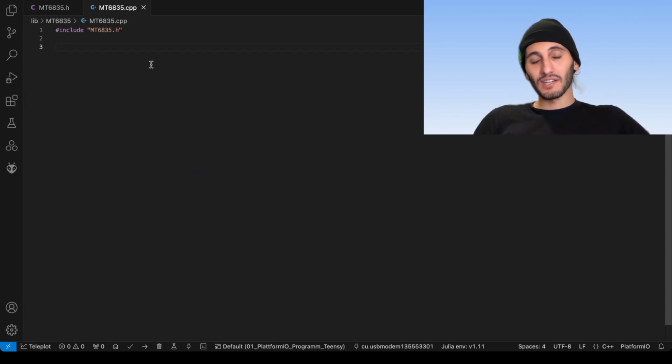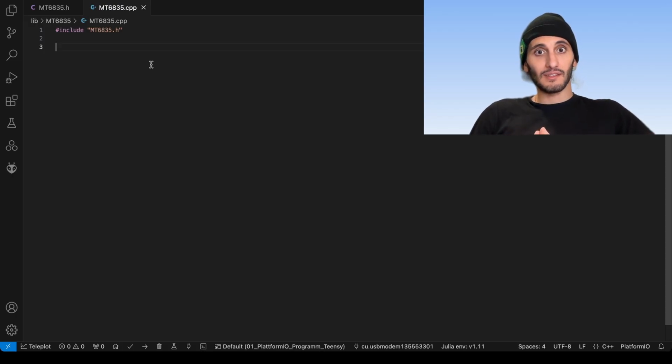Later is now. I am using a Teensy 4.0, which has multiple SPI interfaces. So each interface has a different chip select pin, and chip select pin is a parameter in my class or in my object for my class, okay? So depending on which chip select pin I use, I have to use a different SPI interface in my code. And I don't want to always change the code depending on my chip select pin. That's why I have to use my pointer so I can set the right interface for my given chip select pin, okay? So it's all done automatically. I don't have to change my code depending on my chip select pin.